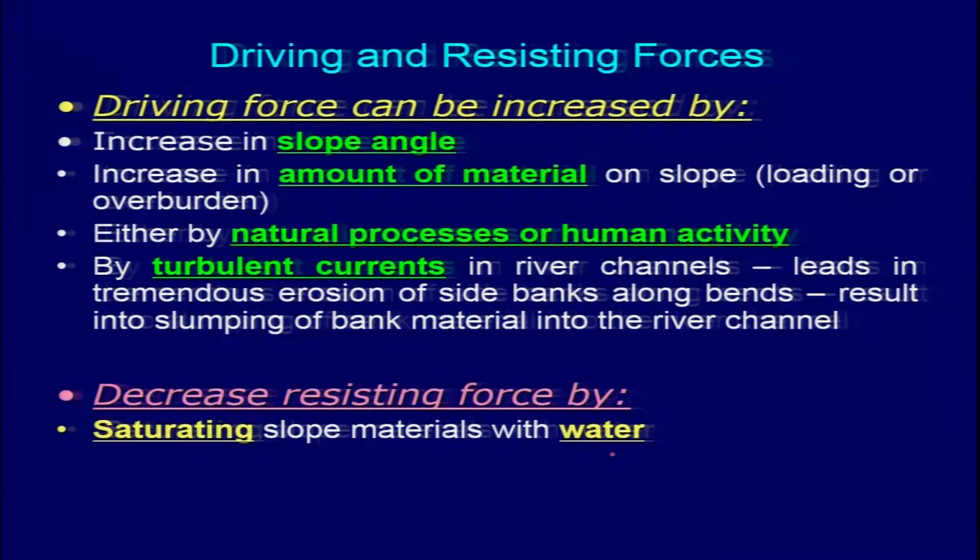They try to construct small waterways or canals so that the water can be drained out as early as possible. If you allow the water to percolate down, the material may get oversaturated, which will result in a decrease in resisting forces.